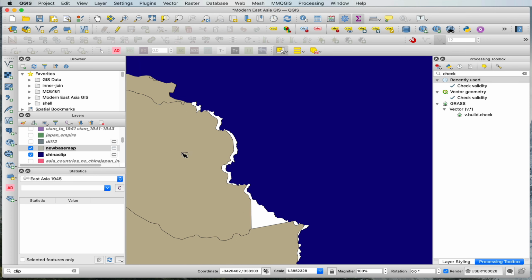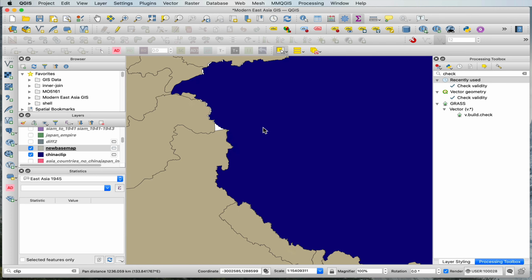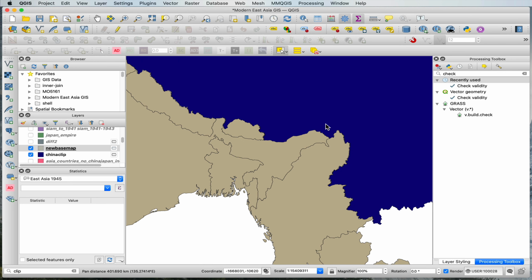I need to repeat this process for each of the bordering countries. You can't do it all at once, because in that final stage where you're merging the polygon, if I had just merged the polygon with Russia, then obviously I would be granting Russia territory along the border of Burma. So doing it by country is a way that you can ensure that the final step attaches the territory to the polygon in the less accurate map for the appropriate country concerned.